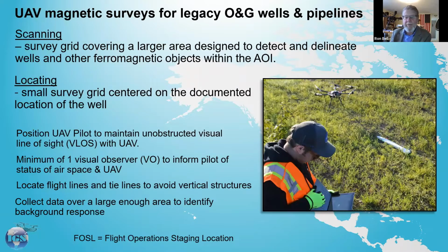And then once I have the magnetic signature of the well, I do some analysis and locate it laterally precisely, within about 2 meters. That's our error in the GPS that I use on the ground. But I also estimate the depth of the top of it, so I can usually be within a foot or two of where the top of that well is.